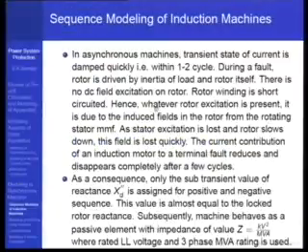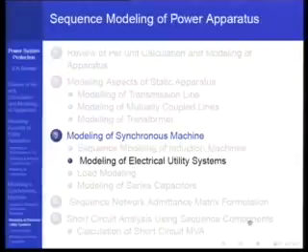Induction motors I will not get much into, because this course really does not go into much of fault currents with motors and so on and so forth. But the point is that what you can take is a subtransient reactance to begin with immediately after the fault for an induction machine, and subsequently you can just put it by its nameplate impedance value, or whatever, kV square by MVA as in a short circuit analysis.